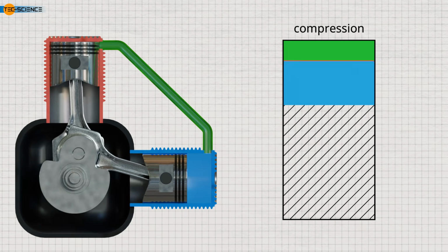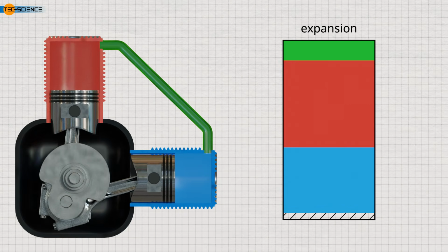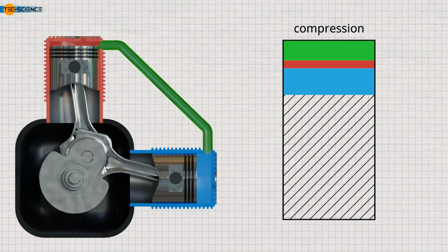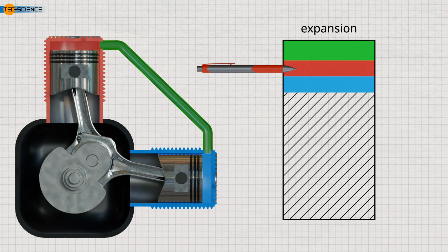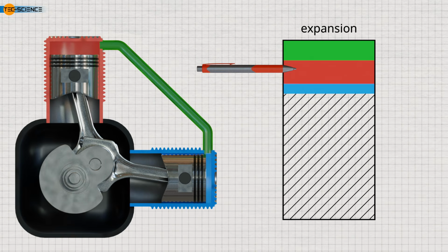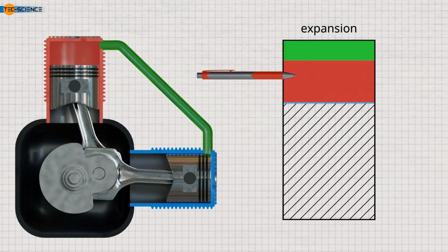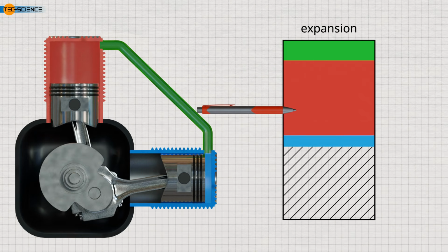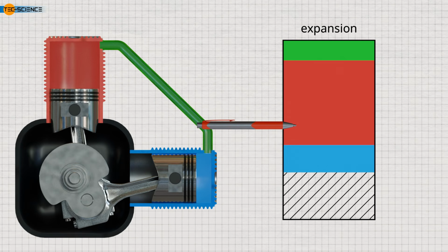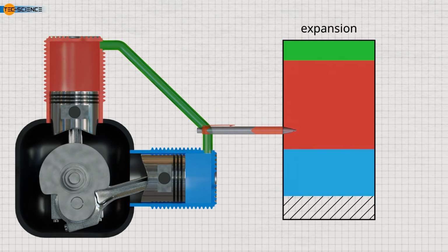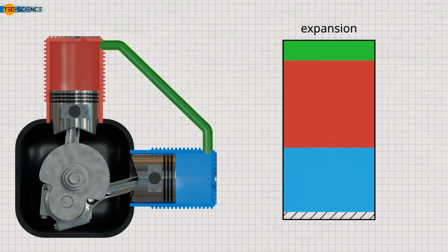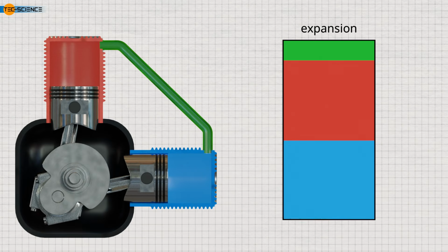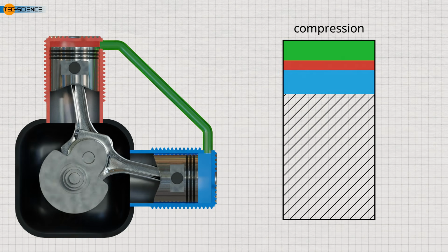Let's compare the two cylinder volumes during the first half revolution of the crankshaft. During this phase, the volume of the heated cylinder increases much faster than the volume of the cooled cylinder. Consequently, there is more gas mass in the heated cylinder than in the cooled cylinder. The pressure is also relatively high during this expansion process due to the relatively large proportion of heated gas. The expansion work done by the gas is correspondingly high.